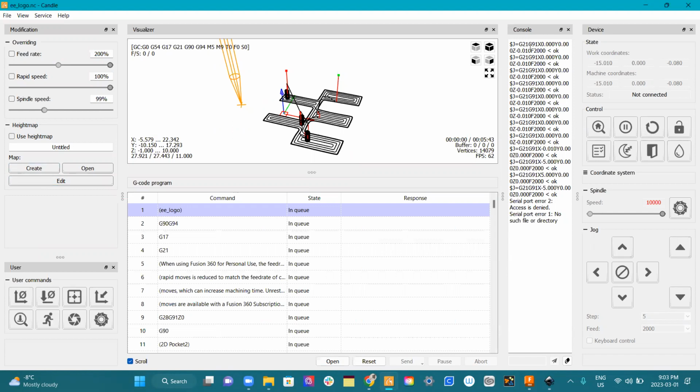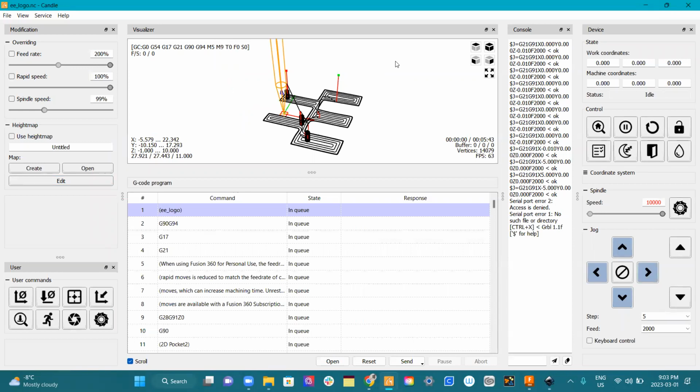Now notice it thinks the drill bit is over here, and it's gonna start drawing over here, and also this is in some random place. So we don't like those things. We gotta start it in a sensible spot. So it doesn't have any of the safety switches. They do two things. They're not just there for keeping it from ripping itself apart when it slams into a wall. They're also there for starting it up. So when you turn it on, it'll bump into the wall and bump into the other wall, and it knows it's in the corner. So anyway, I didn't set that up. That's called a homing routine. And there's even a button here that'll pre-do those things.